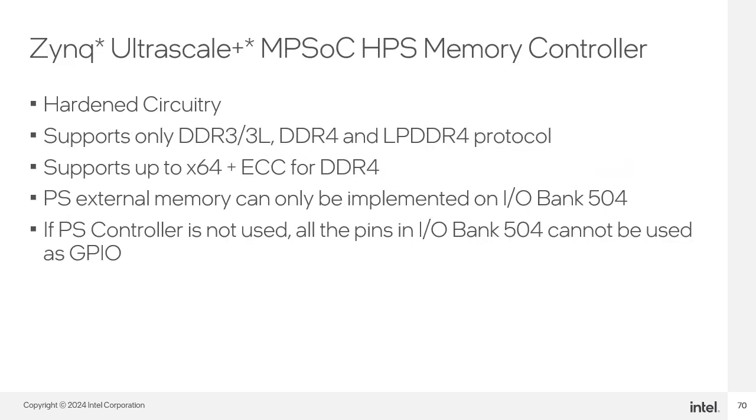The Zynq MPSoC processor system hard memory controller uses hardened circuitry. It supports only DDR3, DDR3L, DDR4, and LPDDR4 protocols. The processor system external memory can only be implemented on its dedicated I/O bank, and you cannot use this bank for any other purpose when the PS memory controller is not used.